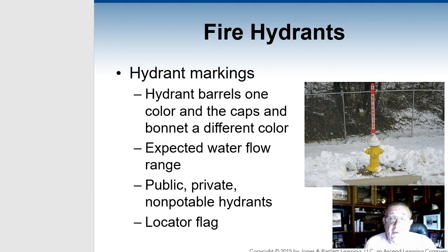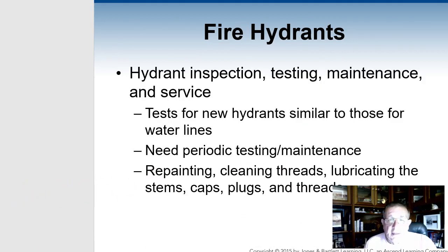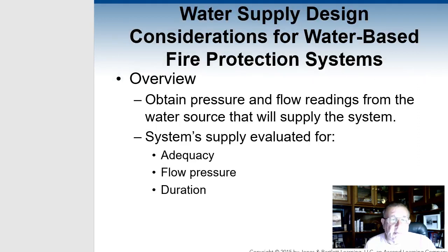When you look at all this, you see how important it is to mark the hydrants appropriately. We also need to put some flags out there when we're dealing with frigid temperatures and snow, so we know where the hydrants are at. It's important that we inspect the hydrants and flow the hydrants, and more than anything else, we keep the hydrants clean, painted, and lubricated at all times. If you don't do that, when you go to need that hydrant, it won't be operational.